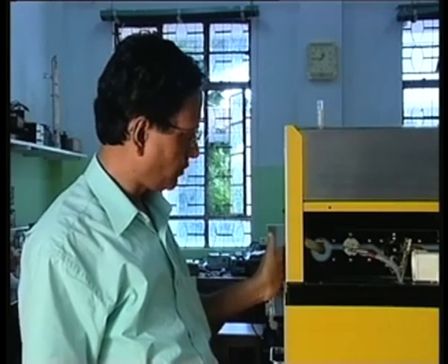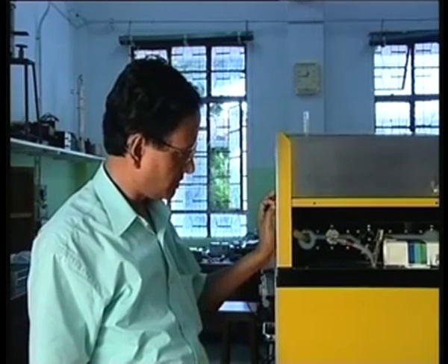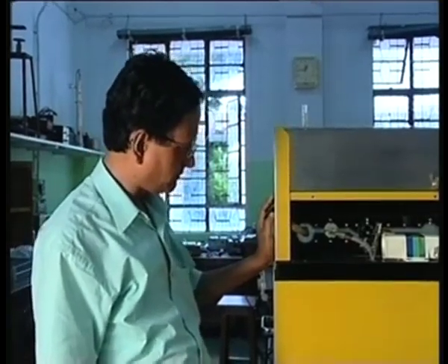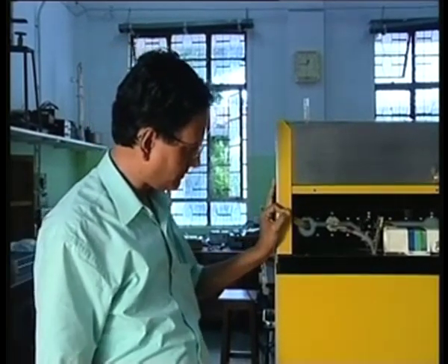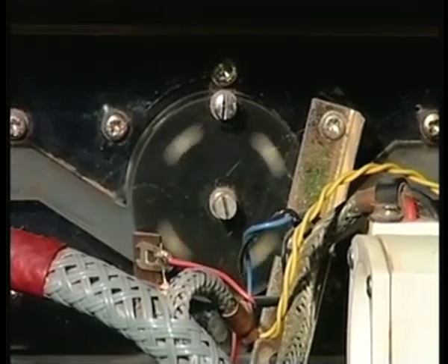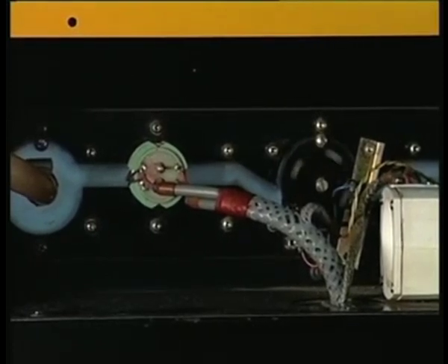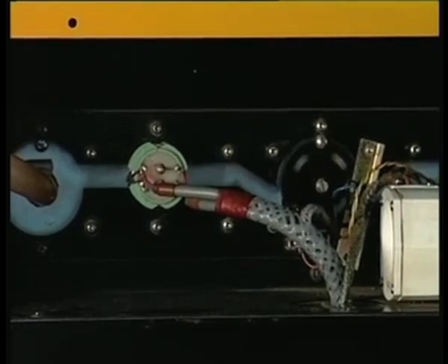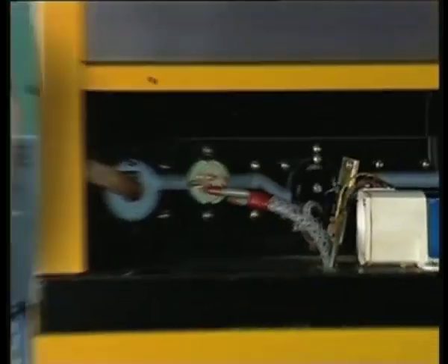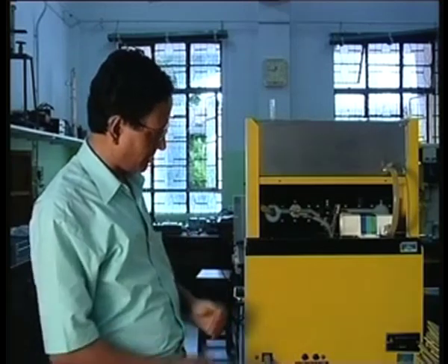See here at the back side of this flow meter system, even though you cannot see clearly the hot wire anemometer, which is also a resistance based flow meter, and the electromagnetic flow meter, you can see here the electro-optic flow meter. What will happen in this instrumentation system is that a light source is launched, and there are 4 white or silver spots on the back side. Light gets reflected from that, and there is a receiver on the other side. So for each complete rotation of the system, you will get 4 clock pulses. If I can count the number of clock pulses, you have to do a little signal processing, in the sense that you have to pass the signal through a signal shaper like a Schmitt trigger.